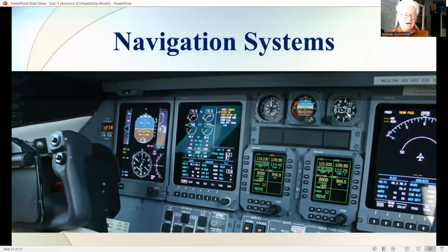And now let's move to another subtopic of today's lecture. It's called navigation systems. Accurate navigation information, that is the aircraft's position, ground speed, and track angle, the direction of motion of the aircraft relative to true north, is clearly essential for the aircraft mission, whether civil or military, right? Navigation systems can be divided into dead reckoning, DR, systems and position fixing systems. Both types are required in the aircraft.